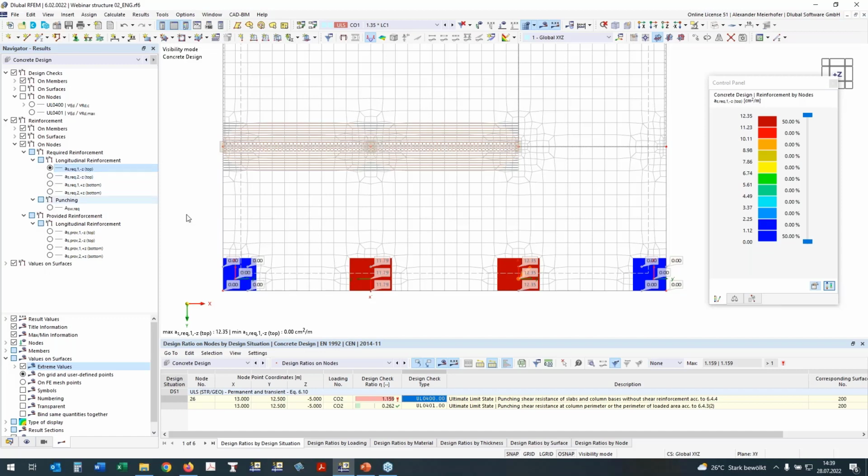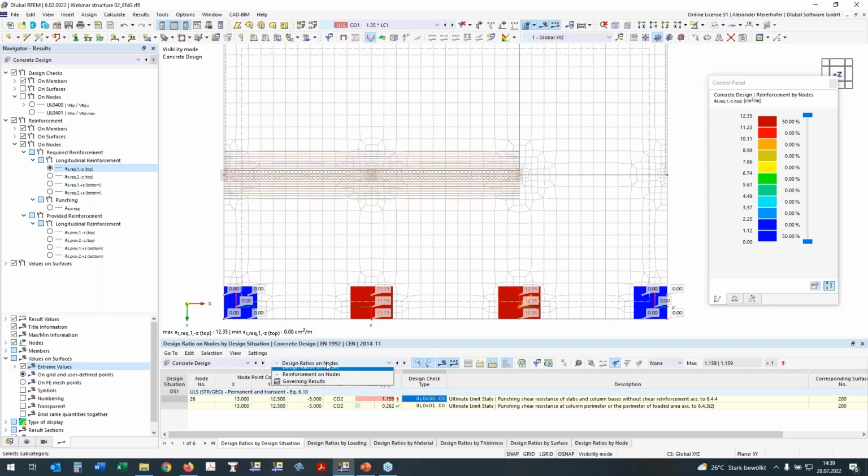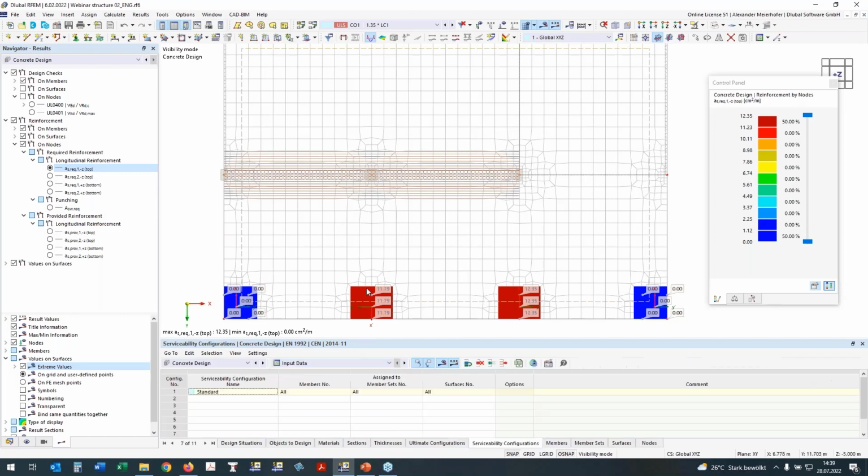but we need then longitudinal reinforcement. In the configuration, I said, please calculate the required longitudinal reinforcement to avoid shear reinforcement. And we see if we would place this at 12 or 13 centimeters, everything would be nice. I will now define the missing reinforcement.